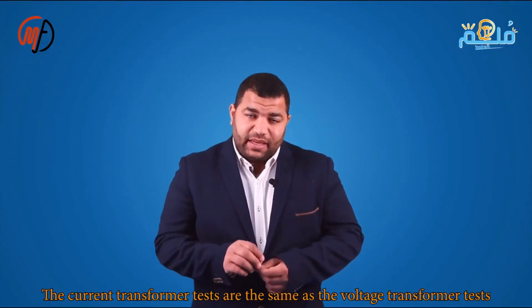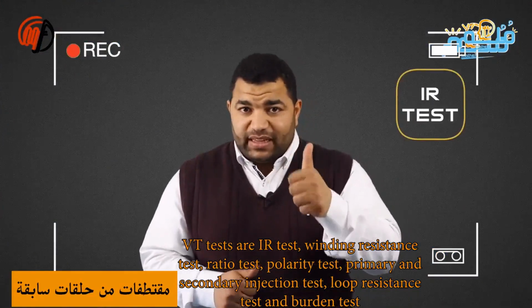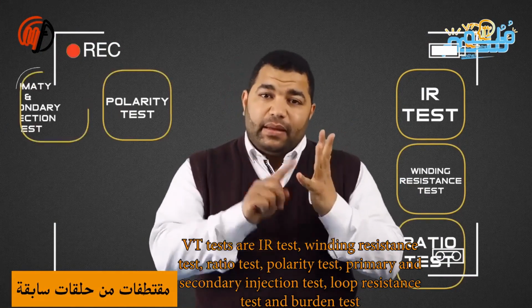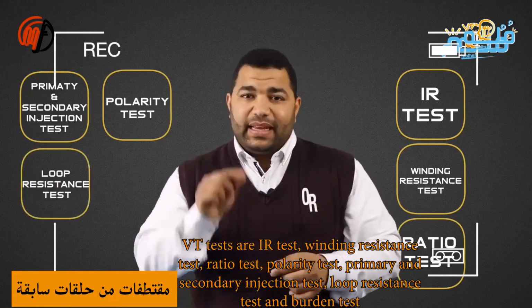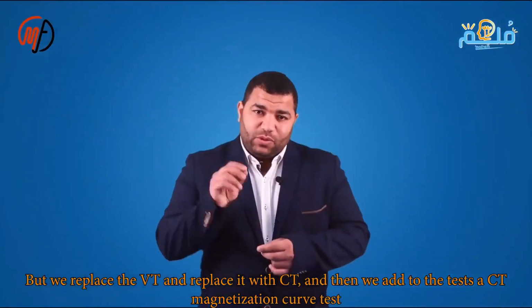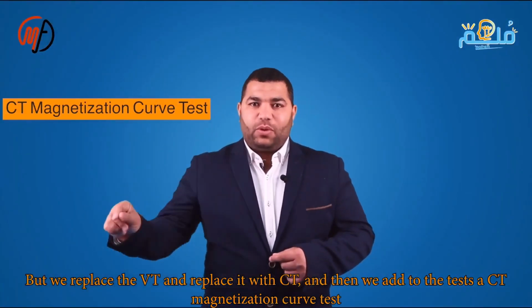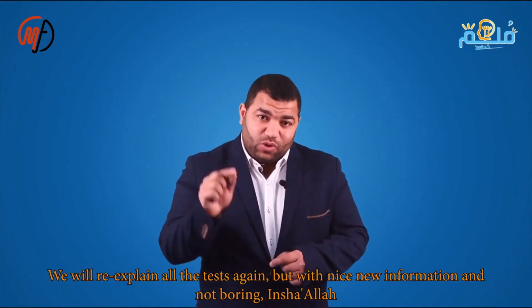As for the CT tests, they are the same as the VT tests, and the VT tests are the insulation test, the winding resistance test, the ratio test, the polarity test, the primary and secondary injection test, and let's not forget the loop resistance test in addition to the burden test, but we replace the word VT with CT and add the CT magnetization curve to it, and we will explain all the tests again, but with new, beautiful, and non-boring information, God willing.